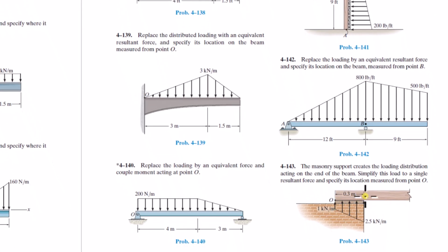Here's a piece of wood. I'm sure it has a load on it, hanging off the edge of a structure here. It wouldn't be uniformly distributed. It would be kind of triangular like that, right? But again, you could do an FEA analysis, put load cells and other instruments on a situation like this and get what the exact load distribution is. I guess maybe it's hyperbolic or something, but depending on your problem, this should be fine. Maybe even a uniform distribution is fine.